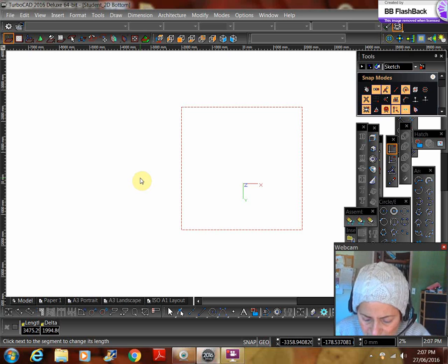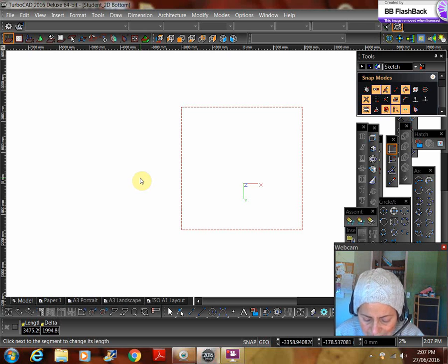To assist with the visualization of the coordinate system, work planes are used. This red one is a work plane. The work plane is represented by a red broken line, a square, which will be displayed in relation to the current user coordinate system and adapts to each viewpoint. The work plane responds in accordance with the user coordinate system and always lies parallel to the XY plane of the user defined coordinate system, with the z-axis lying in a perpendicular direction to the work plane.